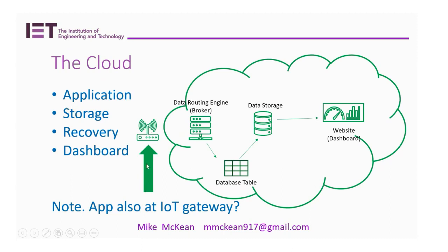So what often happens is you'll install an application on the gateway that says, if my link is down, and if the sensor says there's a fire happening, then I'm going to switch on the sprinklers. And that's very important in the industrial world. You do that for lots of things in the military world, the medical world, and the industrial world. Yes, you will send data back here, but you won't always rely on that 100%. You'll have a default that says if the link goes down, I'll also send a command out from here to a device to do something.